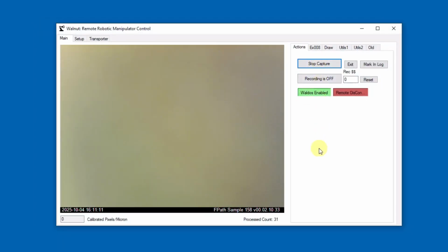So, what can you do if you do not have a moving bed with a known number of steps per micron or a nice calibration slide? Let's imagine a situation where you're looking at a work surface and have a completely unknown resolution. Well, what you can do is place an object with a known size on the surface and calibrate off of that. Here is a small sample of nickel chrome wire which is nominally 0.1 of a millimeter, 100 microns theoretically.